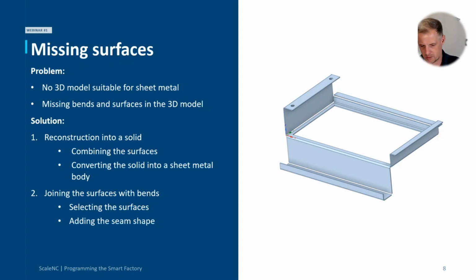Combining on this part everything we saw so far, I can convert solids by using the convert tool. Sometimes it works. If this is not working, I can rebuild bends by deleting the radius, coming back to a sharp edge, which is then possible to convert again into a bend or an overlap, a slit, whatever.